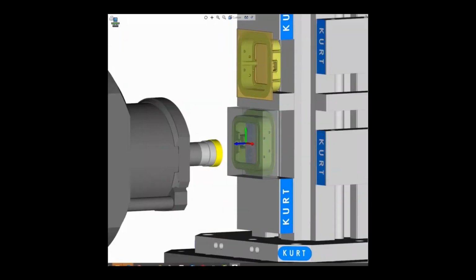And then Brent was talking about doing some roll-in moves. This is a visual of that. We'll see this later, but the roll-in move is a default option within TNG. If you have to use the mold Z-level roughing, in the links, the entry move is called radius and lateral plane. With just the default settings for that operation, it'll achieve that roll-in move that Brent was talking about. What you may want to control is the size of the roll-in move, which is easy to control within TNG. It's just changing one parameter.